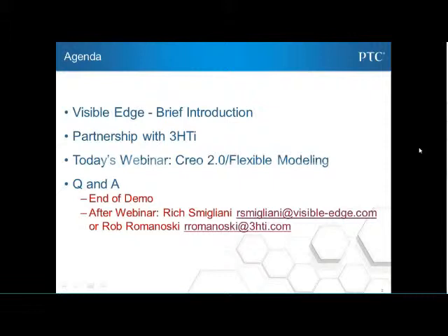See, that's a good point, because a lot of times companies use this to just make a model semi-parametric. Yeah. And that's how they would do that. They would identify the dimensions that they want to be semi-parametric that they can change later on without moving it. So it's extremely advantageous if you have a dumb solid from a customer and you want to apply shrinkage to it without rebuilding the model. You can assign dimensions to the separate features. Absolutely.